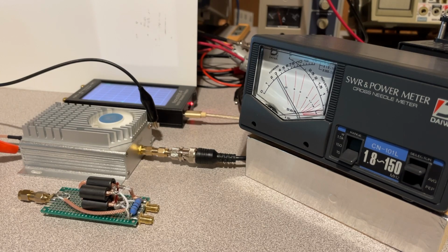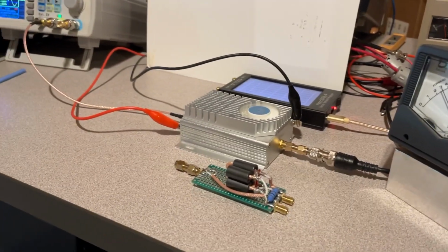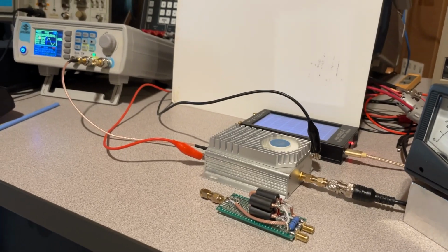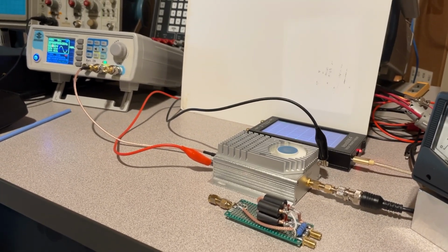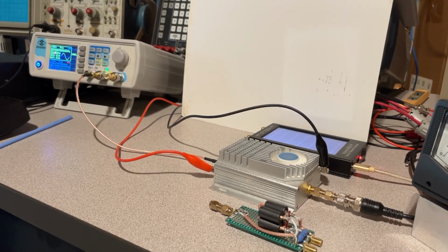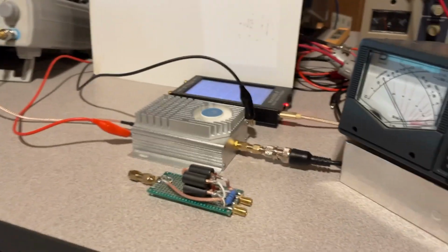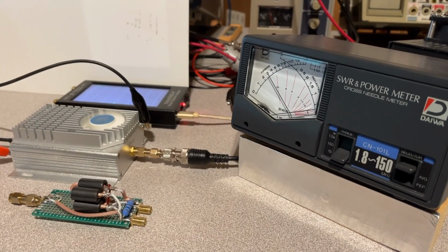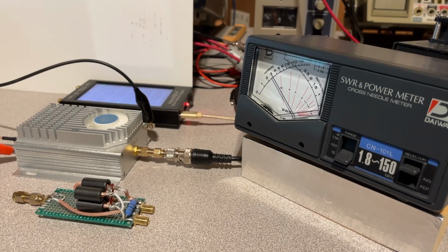All right, so now one final test. Here I have a small 3-watt amplifier, and I'm driving it with a function generator, as you can see there. Basically running it around 20 megahertz and driving it to 3 watts. And we can see the output on the watt meter. So what we'd expect if we connected the splitter combiner and we use this as a splitter, we'd expect the power to be divided evenly.